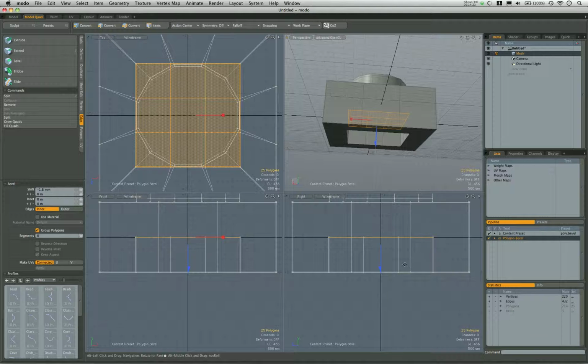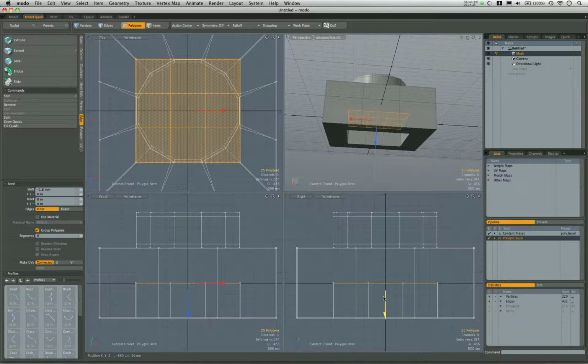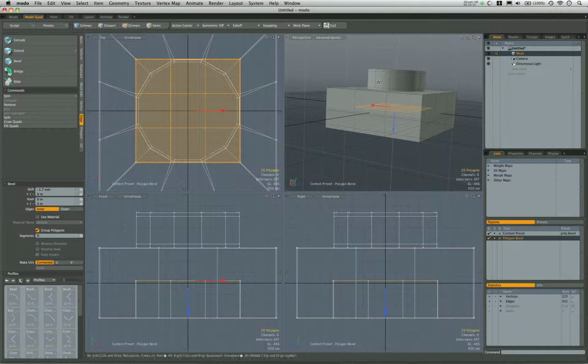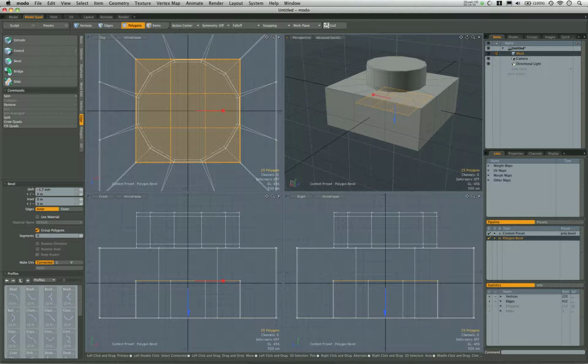And 1.6 millimeters, if you remember, was the height of the button. However, we want a little bit of playroom on this, so I'm going to choose to go up to 1.7 millimeters. That way we won't get any surfaces overlapping. This won't matter unless we do clear pieces, but many of the things that we're going to do, including the set that we're going to build here in this tutorial series, include clear pieces.